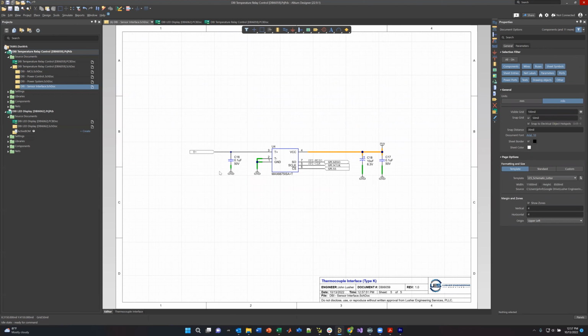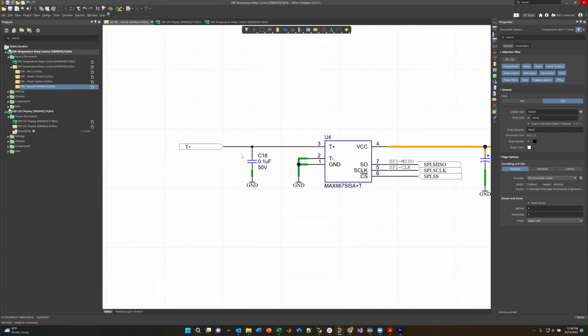In real life, when I got the prototype for this and discovered that, all I had to do was just short the wire. So blue wires and hacking a board is common. By the way, don't be afraid if you get your board in and it doesn't work right away. You don't need to respin the board immediately. You need to get the board working. You make corrections to the board, cutting traces with an X-Acto knife, blue wire, etc. Perfectly normal. In fact, I did that on this design.